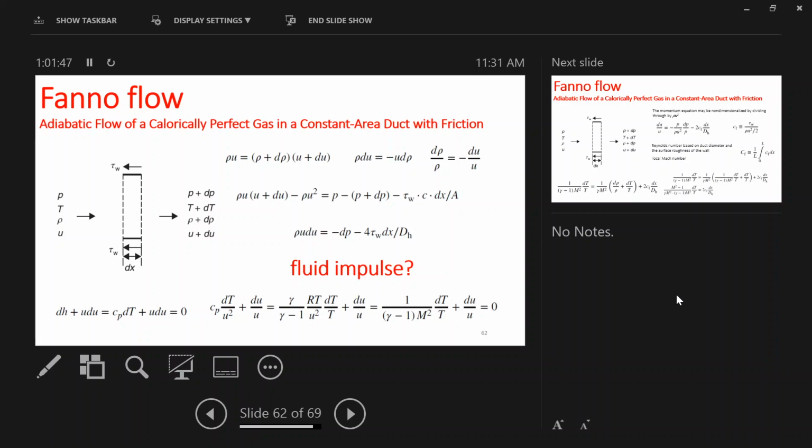And whenever I forget the hydraulic diameter equation, I go from here. So hydraulic diameter of a circle is d, right? And it is related to area and the circumference, right? Area is pi d squared over 4 for a circle, and the circumference is pi d, right? How can this be equal to this? These will cancel out, right?